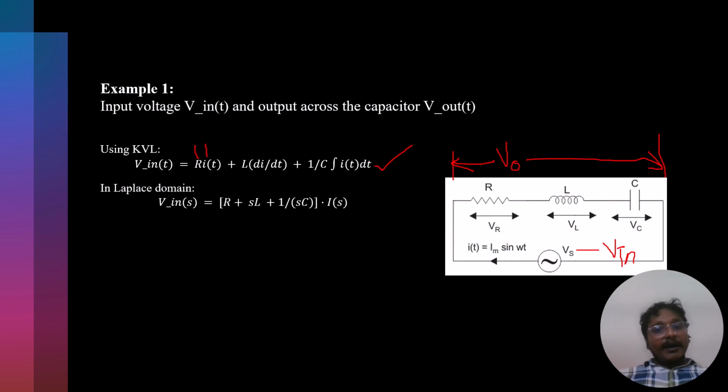You need to understand the conversion of differential equations and integral equations to the Laplace domain, because these are the most common things we will use in the coming equations and video lectures. R into I of s stays as R I of s, L into dI by dt is written as s L I of s, and the integral of I dt is written as 1 by sC I of s.